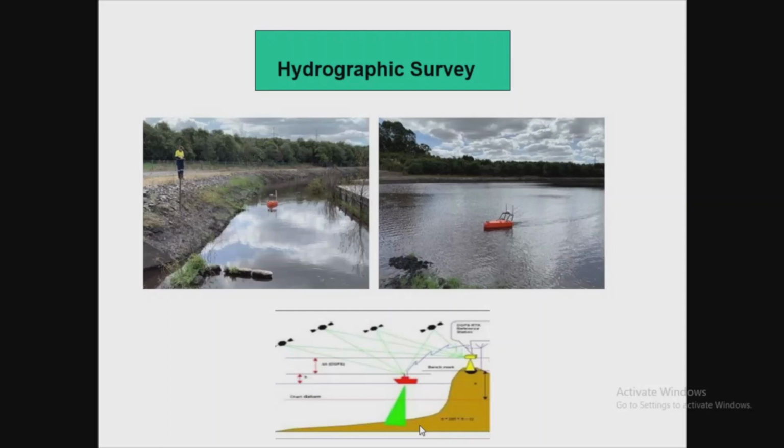And that sheet, if you calculate by the Simpson rule, if you calculate the volume of that sheet, you will come to know how much capacity is enclosed in the reservoir. Because it's a tedious method, and it is only done by specialized persons who have specialized equipment, because it may be a multi-beam type of equipment, or it may be a single beam type of equipment.